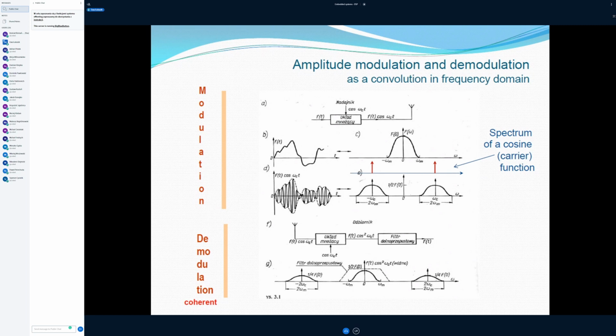Because if you imagine, for example, that the high level of voltage is 1 and the low level is 0, then if we have only ones, we have a continuous high level voltage, and so this is like a stable signal that doesn't change, and its frequency spectrum is just one sample at 0 frequency.